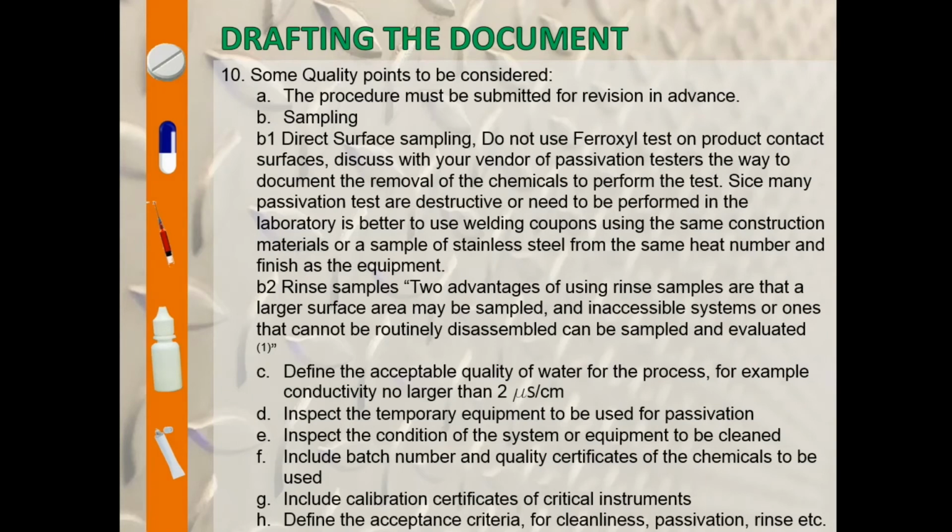Inspect the temporary equipment to be used for passivation. Does it look clean? Is it in good condition? Is it devoted to clean facilities? Take advantage that the equipment to be cleaned is shut down and inspect its condition. Is there any visible debris? Is there corrosion or scale?